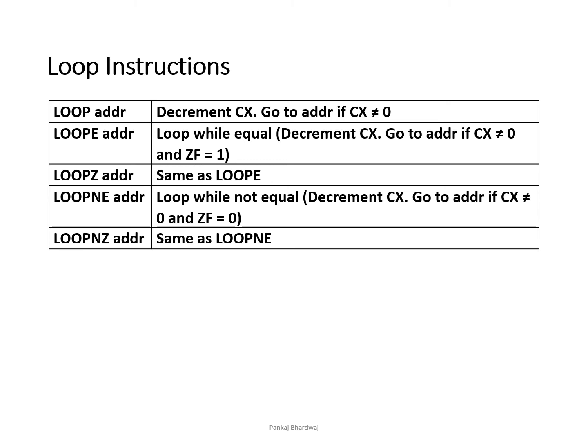Next is the loop instructions. If we are studying the instructions of 8085, then obviously to create a loop, we need a register in which we load the count, and then we decrement or increment one by one based on the program we want to design, and then we check whether it is 0 or equal to a particular value using jump commands.